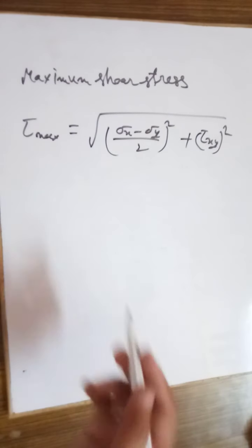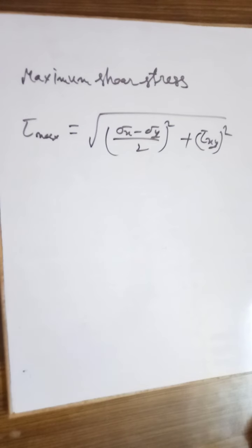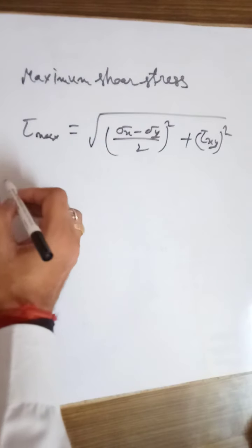Okay, so like this we can find out the maximum principal stress, minimum principal stress, and the maximum shear stress also. So let us take an example.